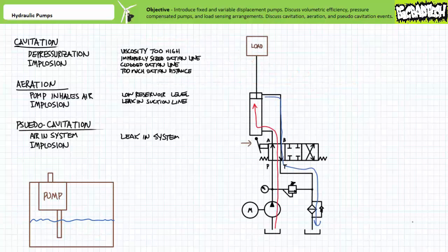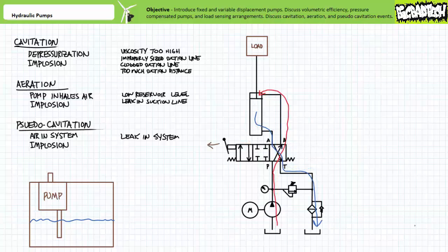Cavitation is not exclusively a pump phenomenon, but can also occur inside valves and actuators. Consider a double-acting cylinder lifting a heavy load against gravity, or tipping or tilting an overrunning or negative load. When the cylinder lifts the load, pressurized fluid supports it. When the directional control valve is shifted into the cross-connect position, pressurized liquid no longer supports the lifted load, and the load and cylinder crash to the limits of travel, and perhaps beyond.